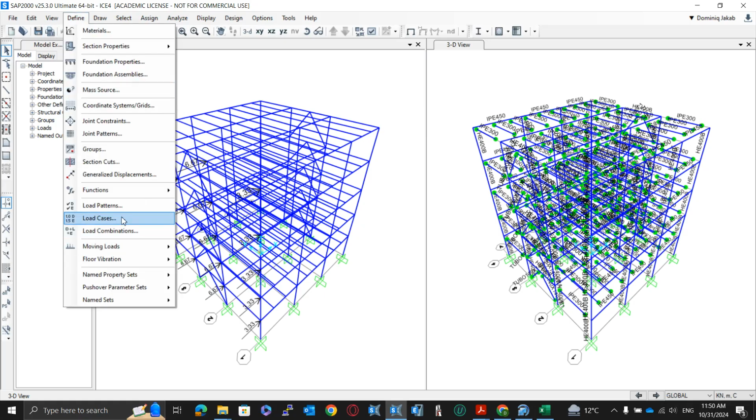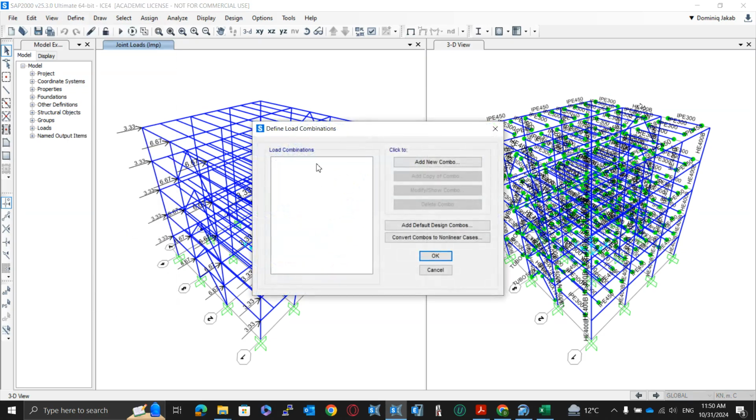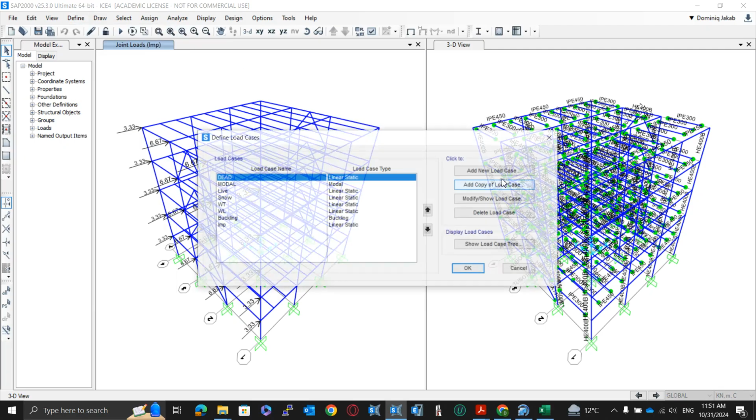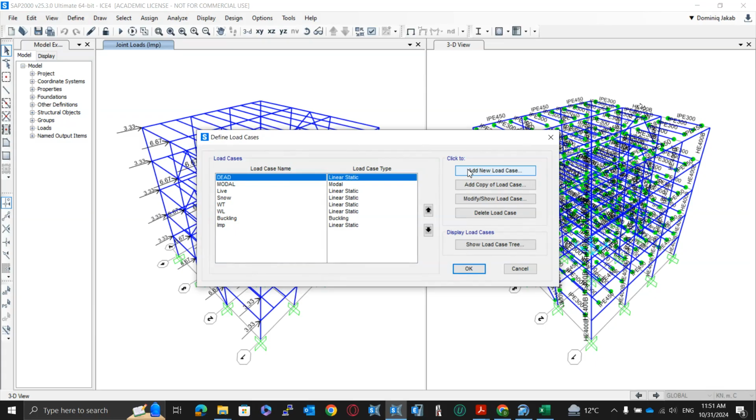Now, apart from this, I want to show you how to take section cuts and relative displacements. So, I need two combinations to define. We will discuss next time also regarding dissipative combinations, because you have to define the case. I will show you the case here. You have two options: either you define the cases independently, seismic action on Y and seismic action on X, or you take a combined action.